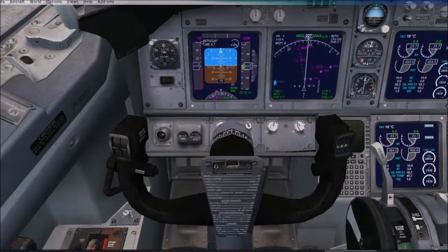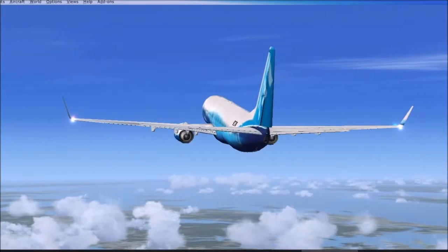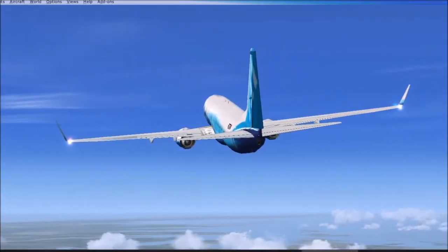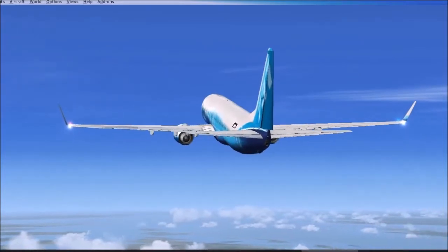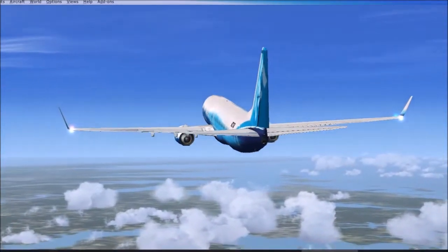The pedals in the cockpit look like this. Look at the floor in front of the yoke and notice how when one moves forward, the other moves back. Not that you'd ever actually turn an aircraft this way, but if you did, this is what it would look like from the outside. When you push on the right pedal, the back of the rudder moves right, which pushes the nose to the right, and vice versa. So the nose of the plane is going to go toward the side you're pushing on.